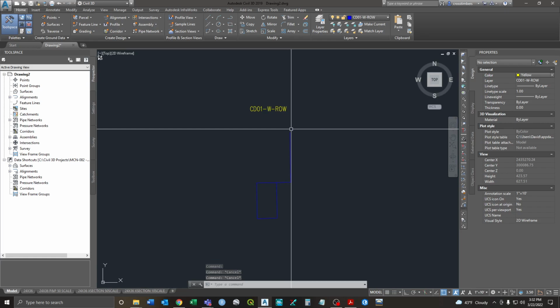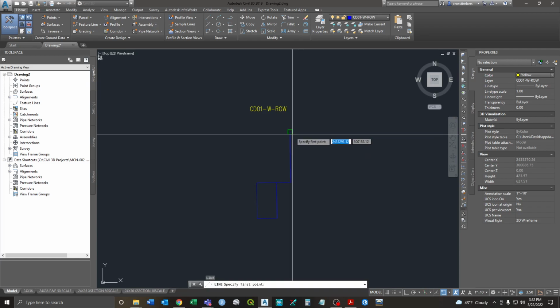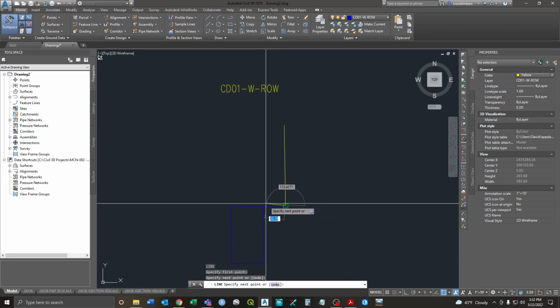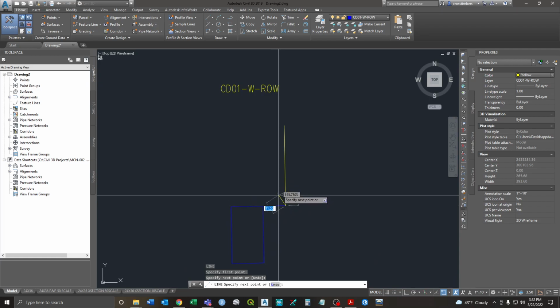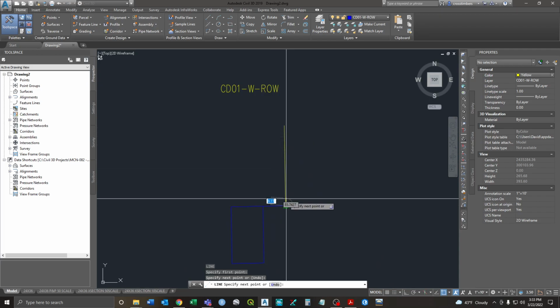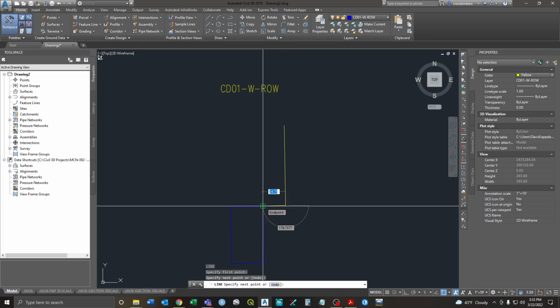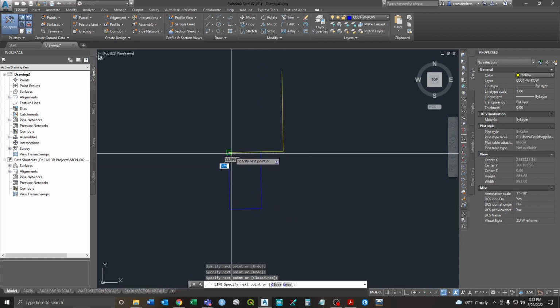But again, we want to start at the spot where we call the section corner. I'm going to hit L, and then if we've got our snaps on, we can do this pretty quickly. So just from there to there. But here, instead of missing this one, we want to snap to here because we want that as a separate segment. Because that's your 24.75. Because this is how far down the section line we go, and then this is how far off the section line we go to get to the point of beginning. So this point right here is what we're going to call the point of beginning, because it's the closest point to the section corner. So we'll click here, and then it's easier to just kind of keep going with that.